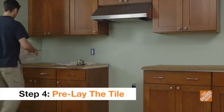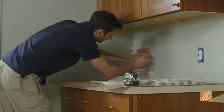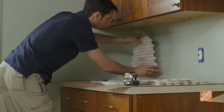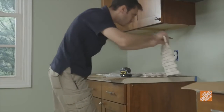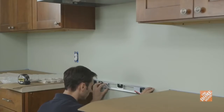Before you permanently tile your wall, consider doing a trial run so you'll know what to expect. Place the tile across the wall and mark your points so you'll know how much tile to use and where to position them. Your starting point depends on the most viewable area of the wall. Then work your way outward and upward. A straight edge or level can help you keep the tile even along the wall.